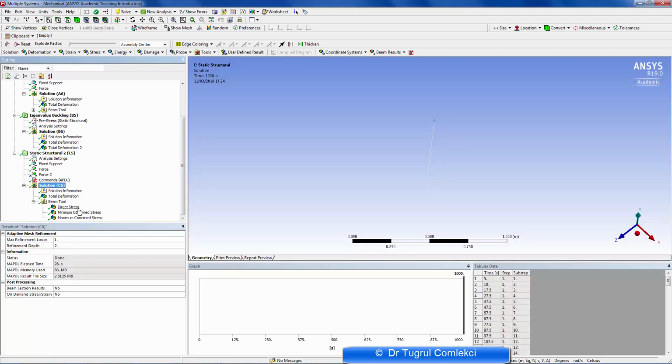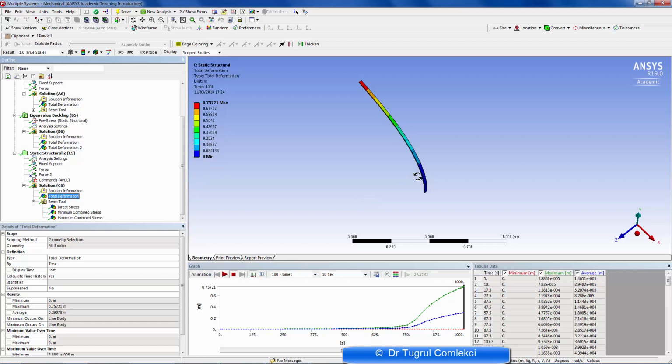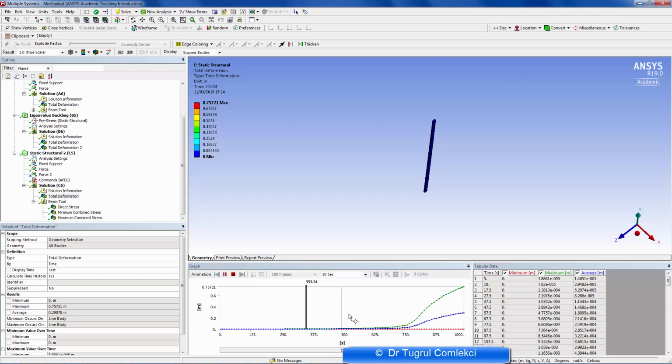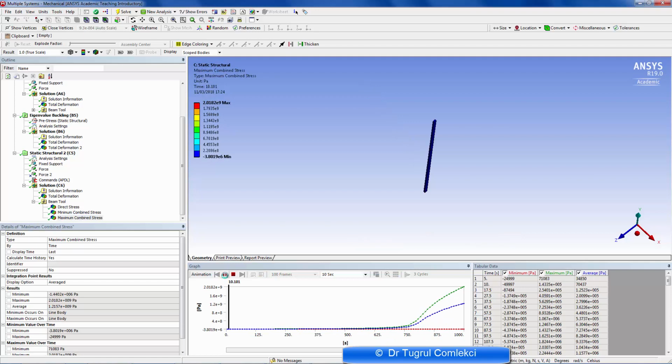And in the solution everything else is the same, and when we run this we'll get a typical simulation that will show that at the beginning the load is carried fine, and as you approach the critical load the model starts to deform and then buckle. And we can look at deformations or stresses at any point in the model. So this completes our buckling tutorial.